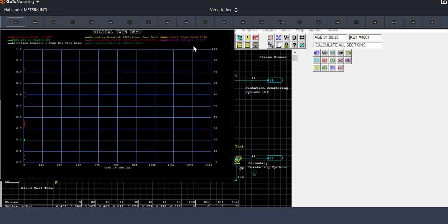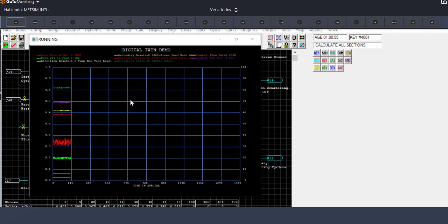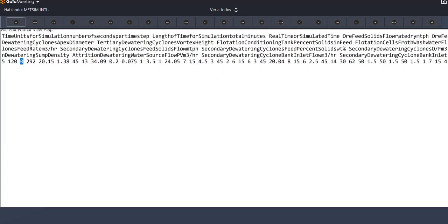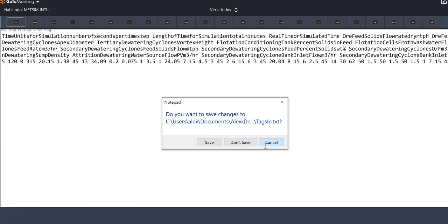And what I'm getting now are results back from the model. So the model is simulating just as fast as it can. You can see here every 5 seconds is being simulated in about half a second or less. And I'm getting information on production rates, feed rates, the phosphate in feed, the phosphate in the product, etc. And as this dynamic model is running, right now our text file is fixed. But what if some other external program wrote into here and wrote that as 315, excuse me.